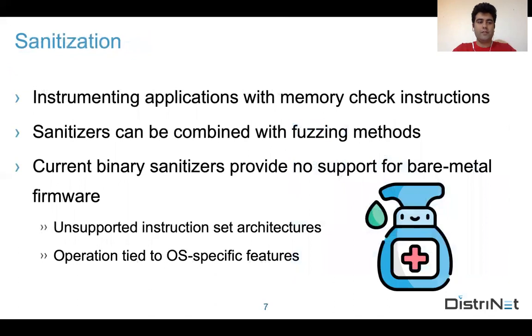Also, sanitization, or memory sanitization, is a method that instruments the application with some memory check instructions. And these instrumented instructions can be combined with the fuzzing method to make these faulty states observable. But the problem is that at the moment, there is no binary sanitizer that provides support for bare metal firmware, because of some unsupported instruction set architectures or operations tied to OS specific features.